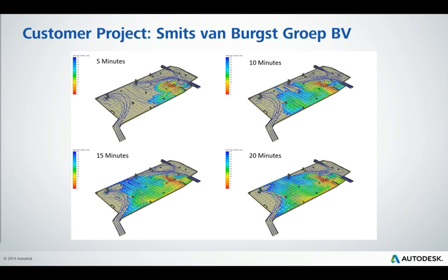And then a case that I ran recently, and the images that I've shown a few times through this model. This was one of the models that we ran for 20 minutes, and we had a fire. You can see on the top left exactly where that started, and you can see over the 20 minutes our room was filling with smoke and our visibility was gradually decreasing. So the blue is where we've got good visibility, but we're gradually seeing yellows and oranges and reds as the visibility decreases.